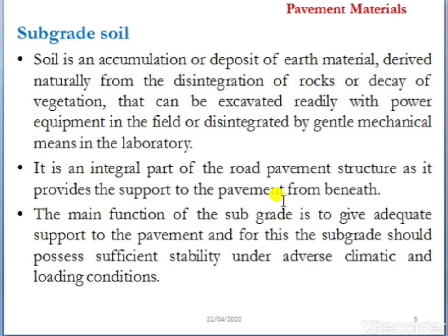So here the formations of waves, corrugations, rutting and shoving in black top pavements and the phenomena of pumping and consequent cracking of cement concrete pavements are generally due to poor subgrade conditions. So if subgrade soil is of good quality, then we can expect a good pavement surface.